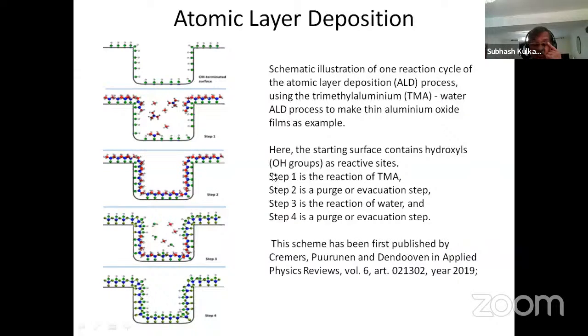So basically they use precursors, chemicals that will make the materials that you want deposition of. So if you want, say, aluminum oxide, TMA is the chemical name, which you purge through. And then very small monolayer is formed, and then you purge again.